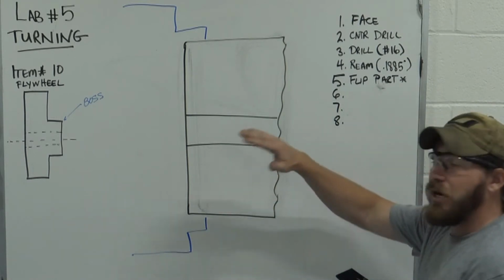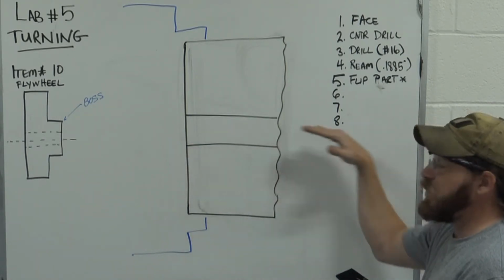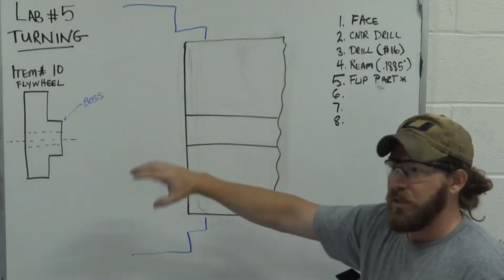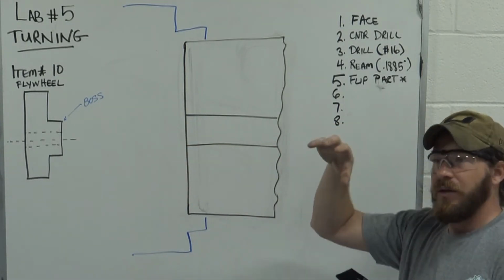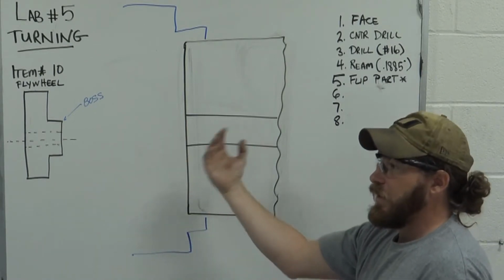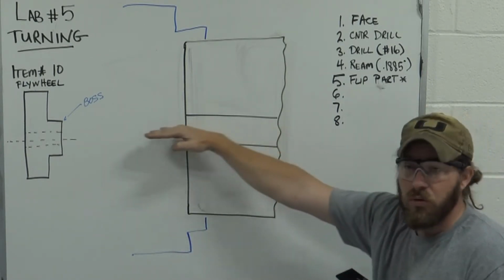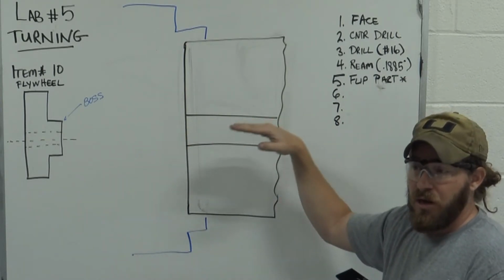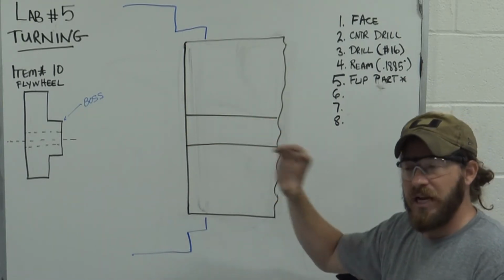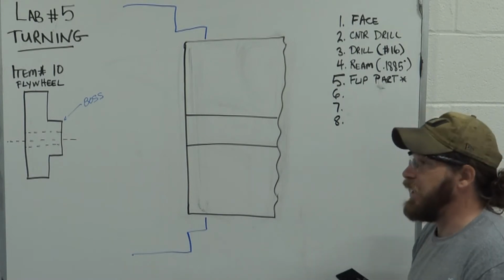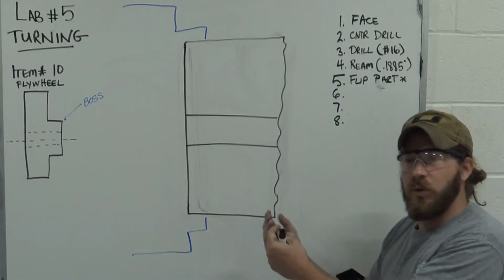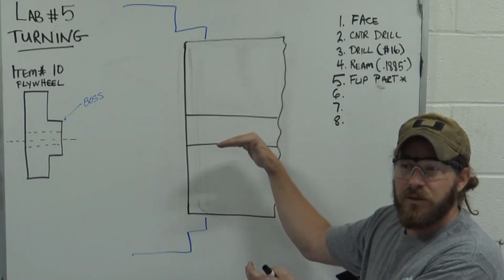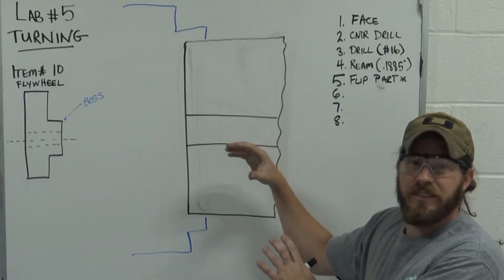All right. So that being said, we put a nice, highly controlled hole right through the center of this. So when I take that out of the chuck and flip it around, I have to ensure that this hole is still going very much on the center of rotation now that I reclamped it. All right. So what we'll do, I'll show you this when I give you the machine demonstration, is we'll use the reamer to replace this back in.